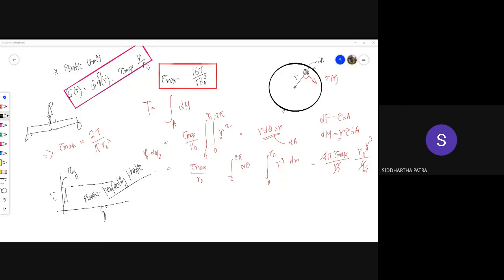It's not a question about the outer layer. The outer layer is obvious, the stress is highest at the circumference. My question is, is there a particular cross section where you have higher stress than any other cross section, much like bending? In bending, you have the highest bending moment at a single section, and that is a section which produces highest bending stress at the boundaries compared to any other section.